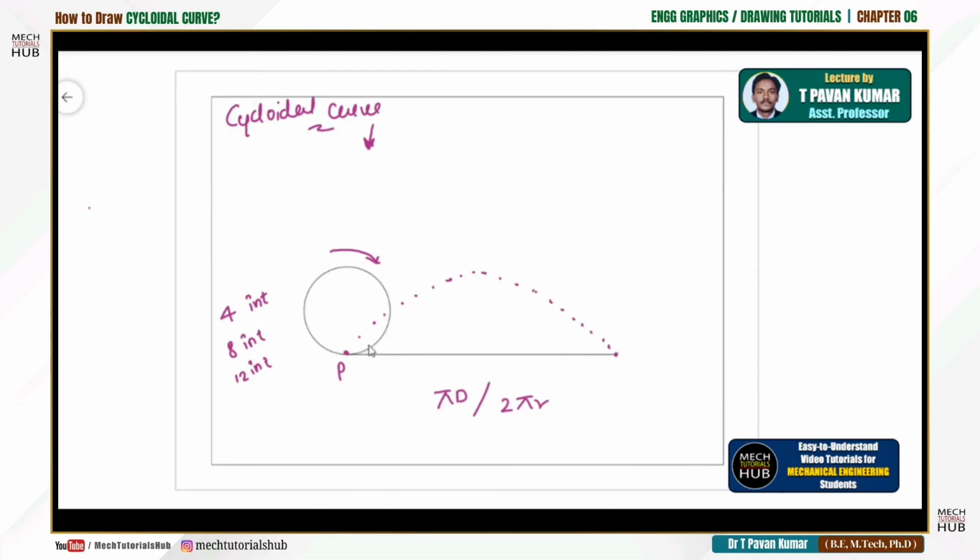It is not that it is automatically going to be created; we have to develop it at the end of the day. So how many divisions you are going to prepare out of this particular circle is more and more important. For example, if you want to make it into 4 divisions, as it is moving 360 degrees, 360 divided by 4 will give you an angle. That angle needs to be followed to divide the circle into a number of segments. And the formula for the circumference of a circle is already known to us from the basics.